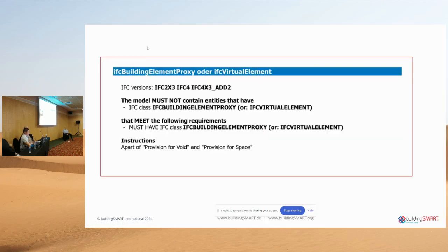It's machine readable. As far as I remember, the BIM coordinator or BIM manager also advised not to use building element proxy, and required that every engineer and architect and whoever will be doing the model should properly map the whole IFC schema.